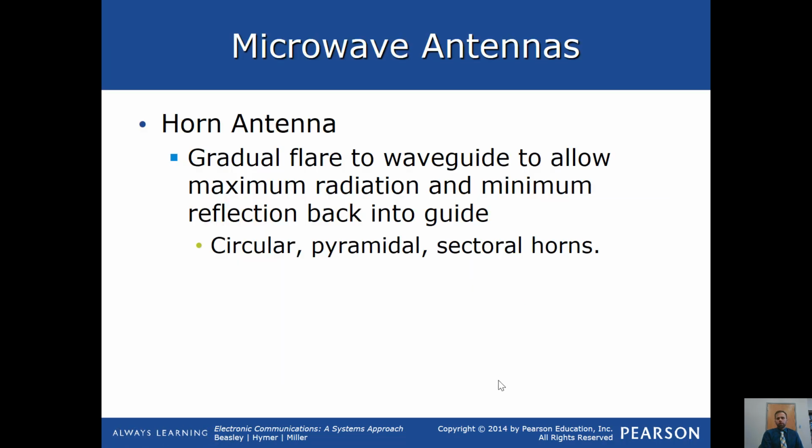Then we have horn antennas. These basically add a gradual flare to a waveguide to allow maximum radiation and minimum reflection back into the guide. And these can be circular, pyramidal, and/or sectoral in shape.